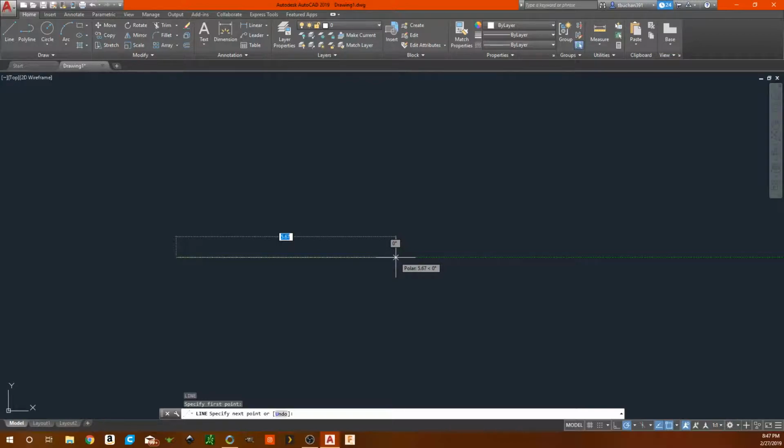But you can either click where you want it to be. Like say we want to get it to 6. See, it's a little tough getting it to 6. But if you start off in that direction and then press 6, enter, it draws the same line. The line command is used for so much in AutoCAD, whether it's laying out a drawing, putting in your models, anything really.